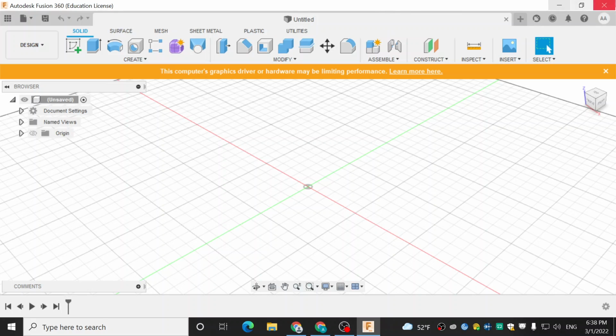All right, so to start us off today, we're going to be talking about construction planes. If you remember, construction lines when you're sketching are those little orange dashed lines that you can draw. They won't make planes or shapes, but they're really helpful in giving you snap points for your actual lines.